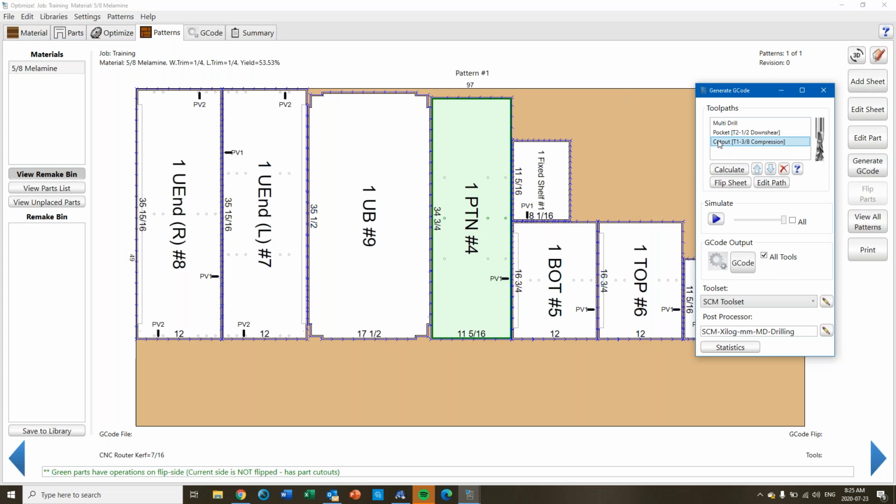So you put a sheet on, you do your flip sheet program, you flip it over, you put it against your pins again, and then you cut the rest of the sheet out. And those are different programs, or it's one program? 2 programs. It has to be 2 programs. One that's called flip, and then the other one is whatever. Exactly. Okay, I understand.